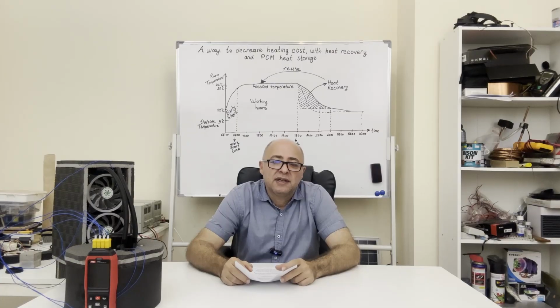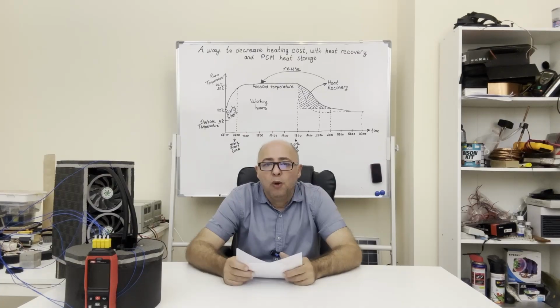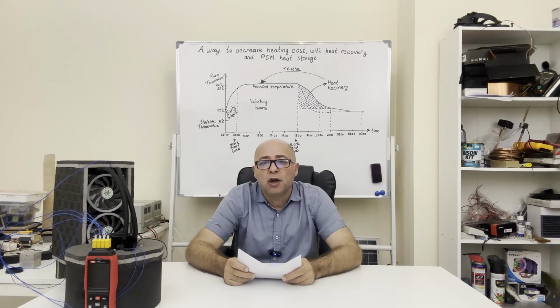In addition, the more objects there are in the space, the more energy is spent to heat them. Although you may not notice it, the heating of the walls and objects continues for 3 to 4 hours. In order to tolerate this, your heating system uses extra energy for the first 3-4 hours, both for heat loss from the walls and for heating the interior objects.